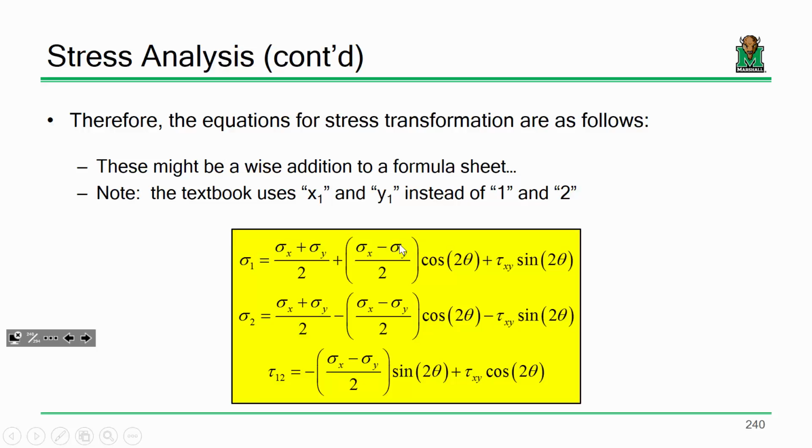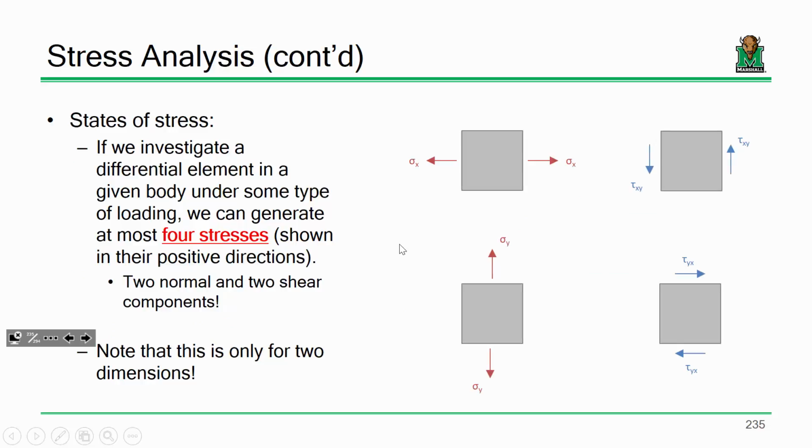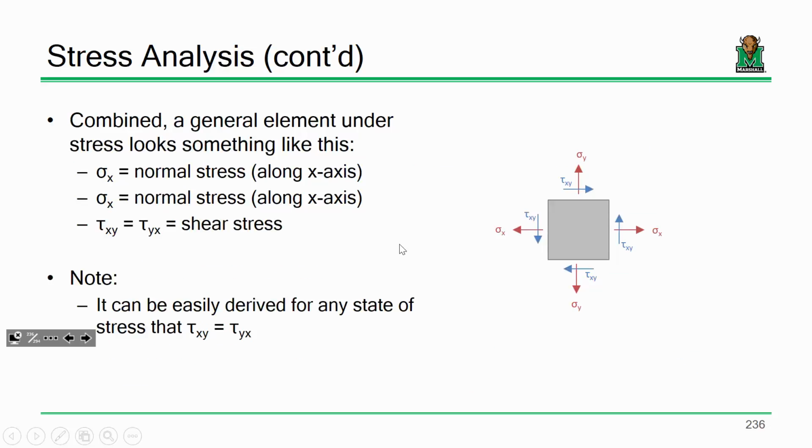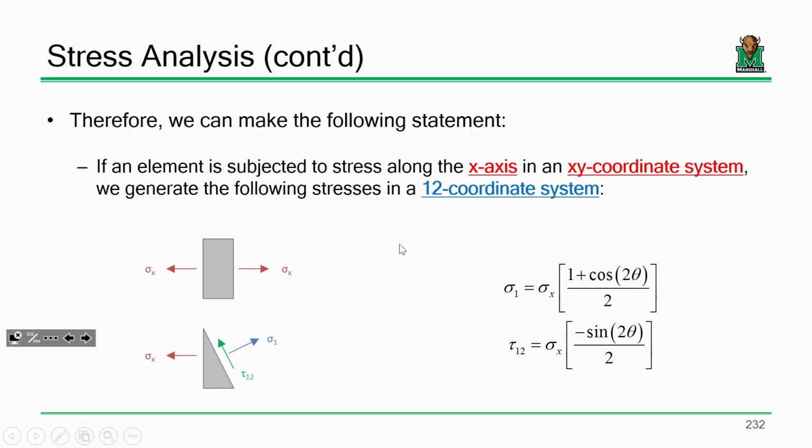And in all seriousness, into the mechanics: when we cut at an angle, we recognize that we're going to be developing stresses that are different. If I have a single stress and I apply it axially, if I cut perpendicularly, it's just the same stress. It's just static. Sum of forces in the x direction must equal 0. But if I cut at an angle, I get different components. I get a normal stress and a shear stress.